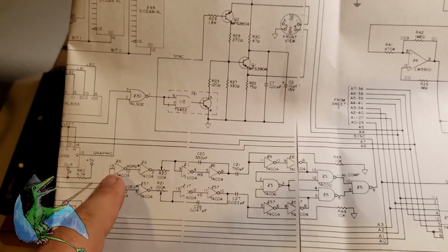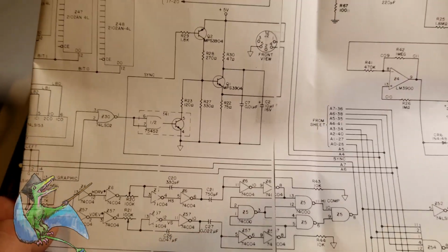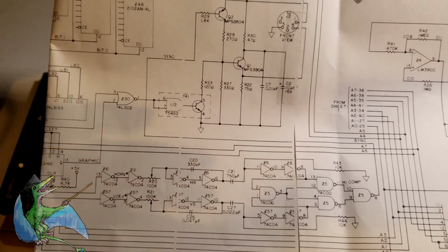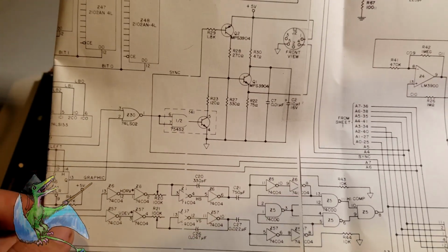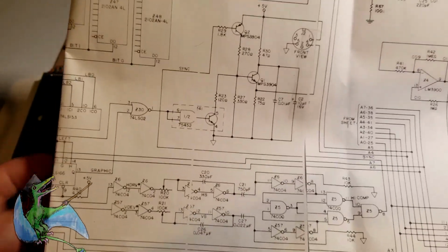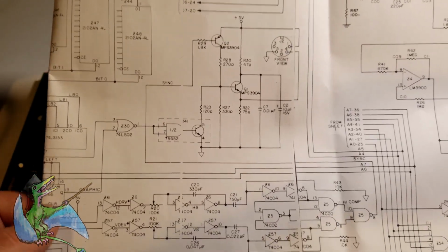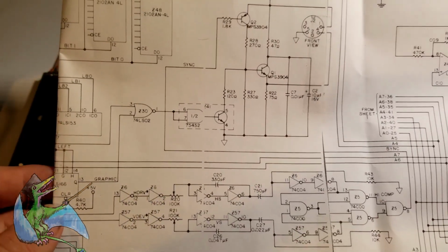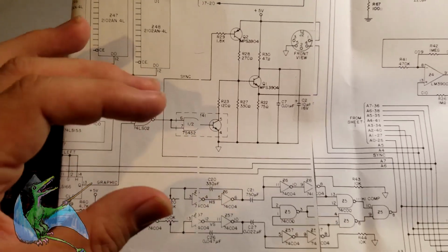So the first step here is that drive pulse, which is coming from TTL circuitry, and this is CMOS. Both are digital circuitry, they have an on and an off, but the difference is that at the time, classic TTL and LS circuitry was quite a lot faster than CMOS circuitry. So it was used for most of the TRS-80, but it's kind of sloppy in that it doesn't run very close to the rails.